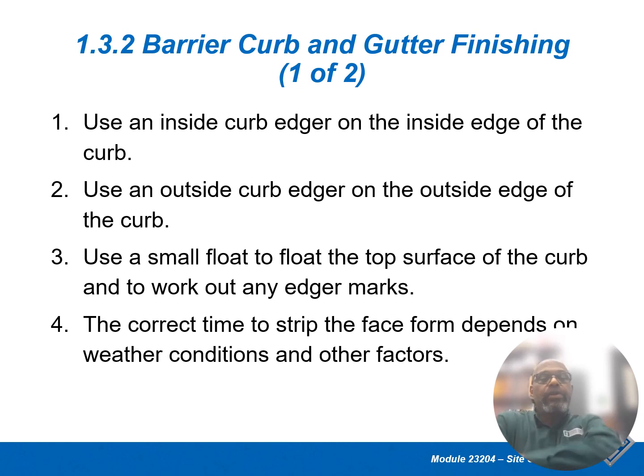So, barrier curbs and gutter finishing. Number 1, use the inside curb edger on the inside edge of the curb. Number 2, use the outside curb edger on the outside edge of the curb. Okay, so again, I kind of went over that, using the inside.